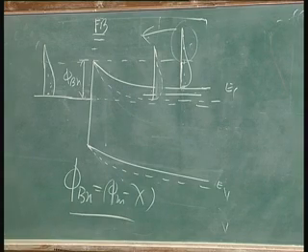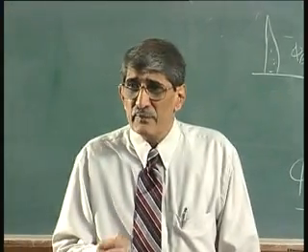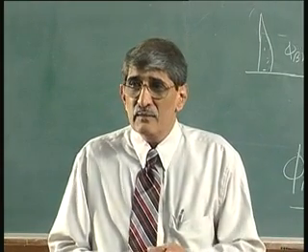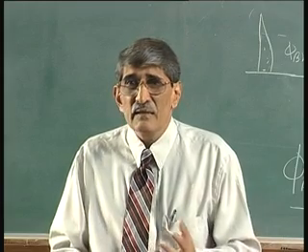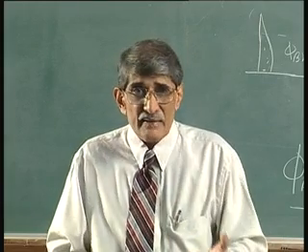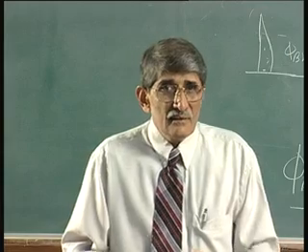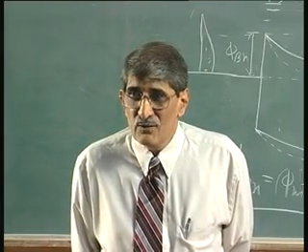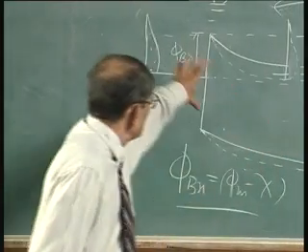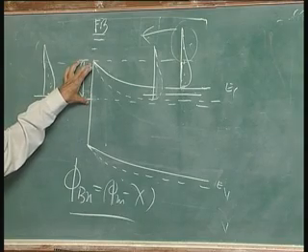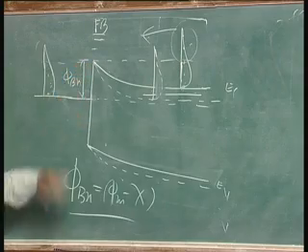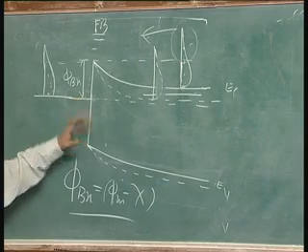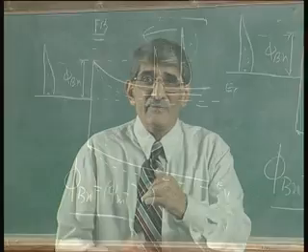So, we look forward to seeing what type of impact these metals really have in making ohmic contact and rectifying contact. We also will see in the case of p-type material what will happen. In the case of p-type material, you talk of phi bp rather than phi bn. If I increase phi bn, you get rectifying in the n-type material. If I increase phi bn, what happens to phi bp? It decreases. So, in a p-type substrate, it is exactly opposite to what we see.